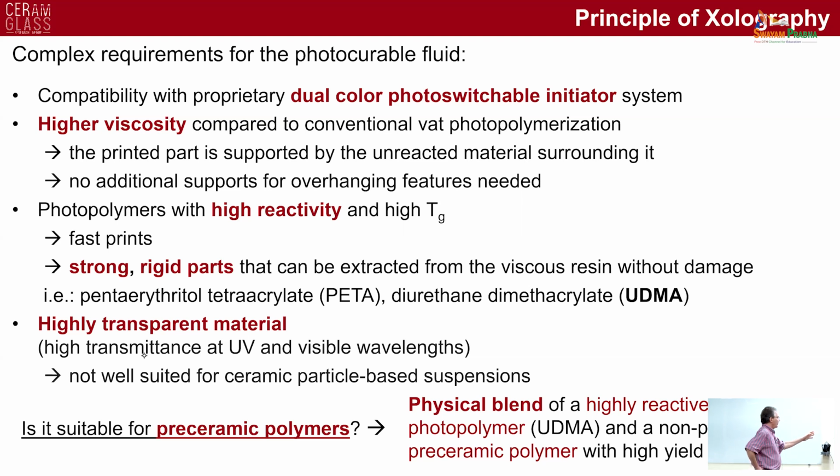So we wanted to use this approach for making parts using precursor-based approaches. And we tested preceramic polymers, and we blended highly reactive UDMA photopolymer, which is something that dentists use.